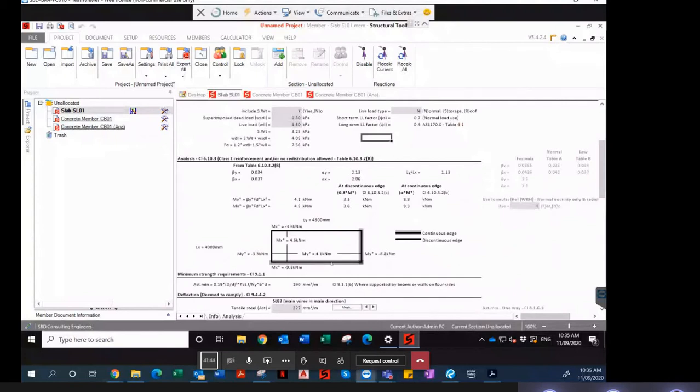The idea why I'm explaining this to you guys is that when we have a suspended slab system, especially on bored piers, it's expensive to have multiple bored piers underneath the slab point load. If it's going down 600-700, it's not too bad. You can dig that and put it in there.